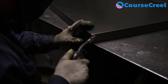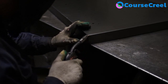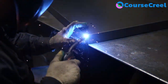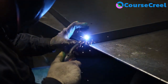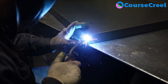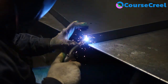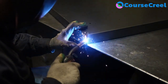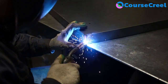On the external surfaces of the plate, oxide is usually present, which interferes with proper fusing, and it can be completely eliminated by using flux. Flux reacts with the oxide and forms low density slag which floats on top of the molten metal, and it protects it from further oxidation. That slag can be separated after the welding process. Slag is a type of impurity which appears after welding. And the flux selection is based on the type of parent metal which is to be welded.